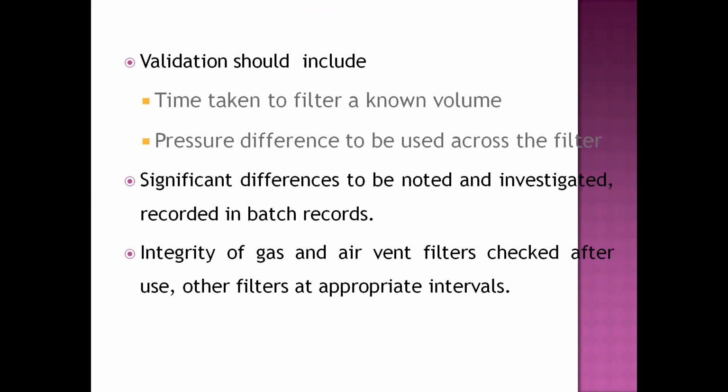And the validations should include the time taken to filter a known volume, and pressure difference. Significant differences to be noted and investigated, recorded in batch records. Integrity of gas and air vent filters checked at use, other filters at appropriate intervals.